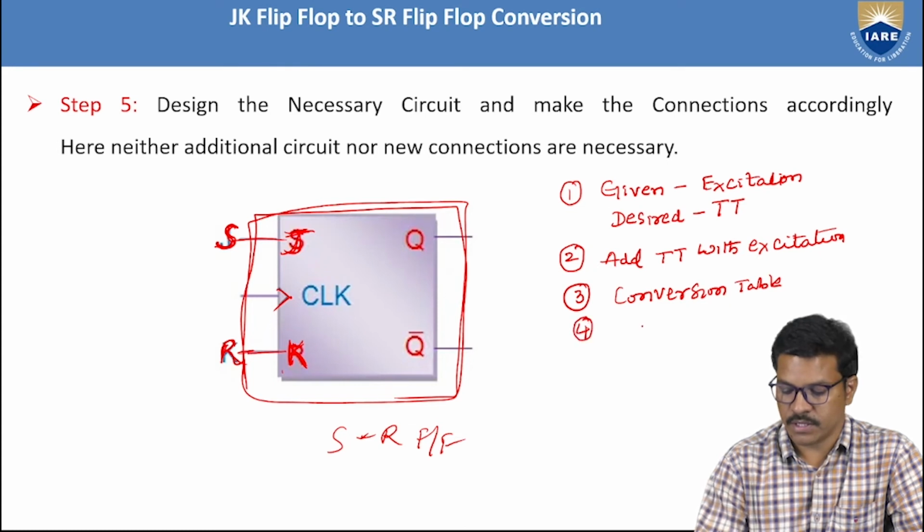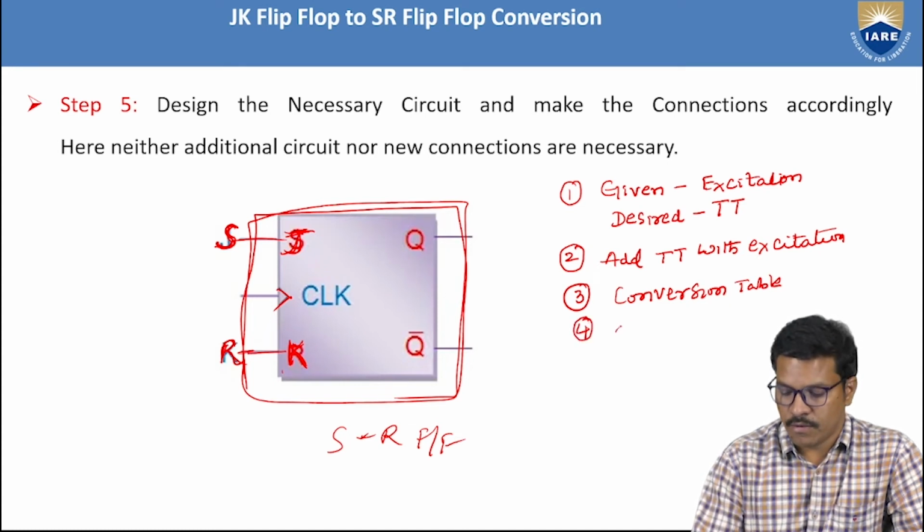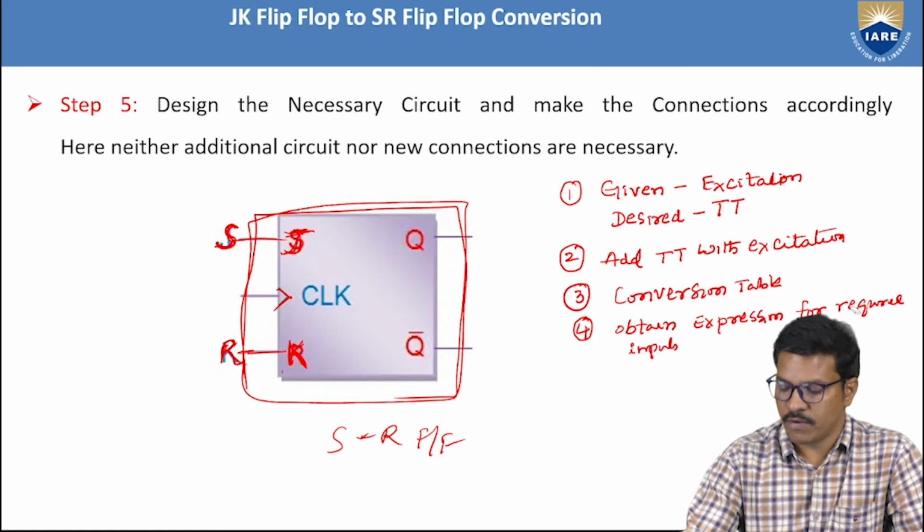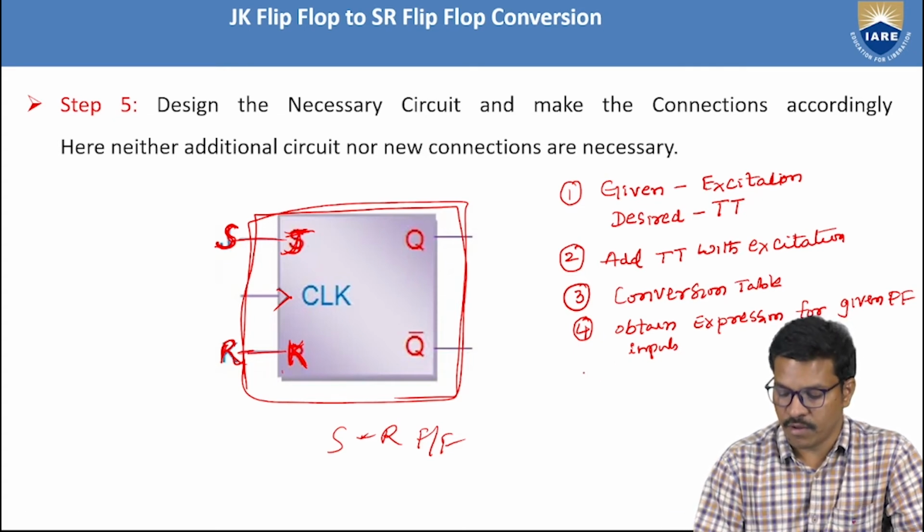The fourth step is to obtain the expressions for the required inputs, like the given flip-flop inputs, so that we can get the required flip-flop, and then synthesis, that is, the logic diagram.